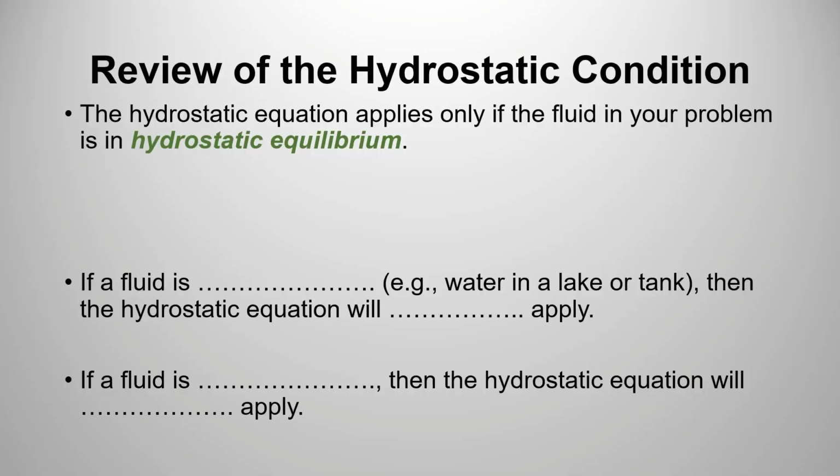I'm going to start with a quick review of hydrostatic condition and hydrostatic equation that we discussed in previous session. The hydrostatic equation applies only if the fluid in your problem is in hydrostatic equilibrium. What is hydrostatic equilibrium? The definition for that would be if the acceleration of the fluid particle is 0 in the coordinate system that you selected, and also if the forces on the particle are only due to pressure and the weight of the particle, then the hydrostatic condition applies and you can use hydrostatic equation.